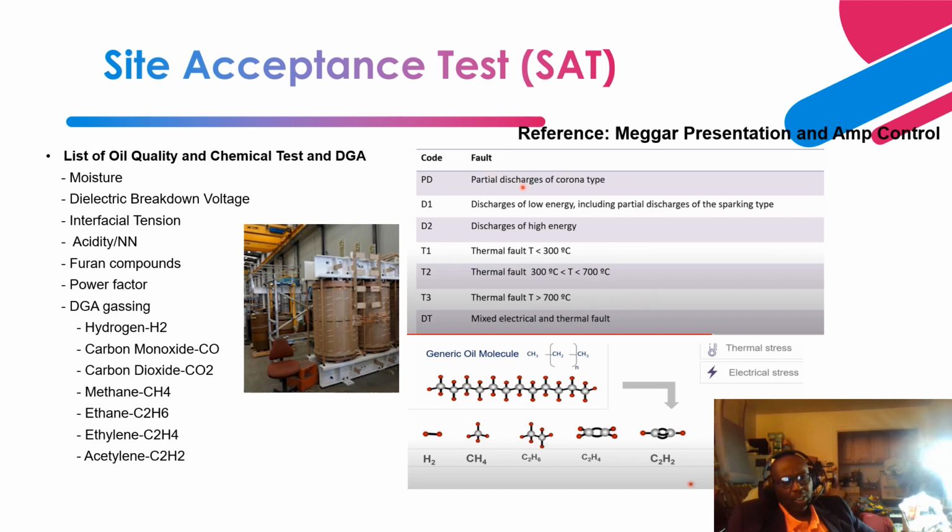Okay, so moisture intrusion basically degrades the paper in the oil, right? So the goal is to minimize and mitigate the amount of moisture. And so that is why during manufacturing, the transformer insulation system is processed. The paper is processed thoroughly, and it goes through different drying processes to remove the moisture, keeping the moisture to 0.5%, right? Okay, so you perform the moisture level ppm, and you basically compare it with an acceptance criteria.